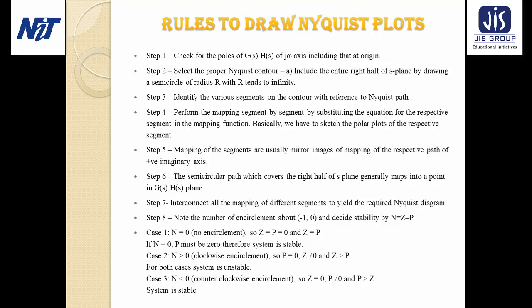Now, if we draw the real axis and imaginary axis, the minus 1 point is located on the minus 180 degree line, and the imaginary part of this point is 0. So, this minus 1 j0 point, or simply the minus 1 point, is known as the critical point of the characteristic equation or the Nyquist plot.